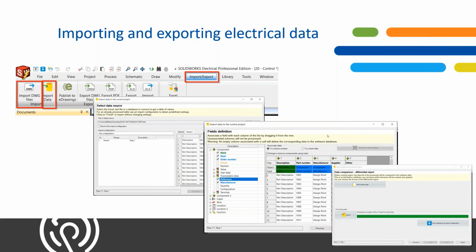You could search for your manufactured parts and start populating your library before you even draw anything, and it's a really quick and easy way to go ahead and start your projects. You could even drop your symbols on a particular page and then start drawing your schematics from there once you know the components that you want, and that will be utilized from the import-export menu.